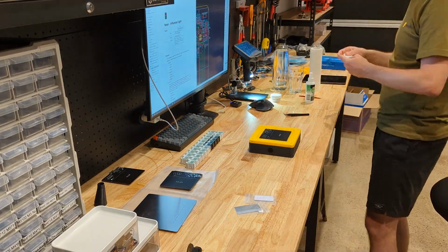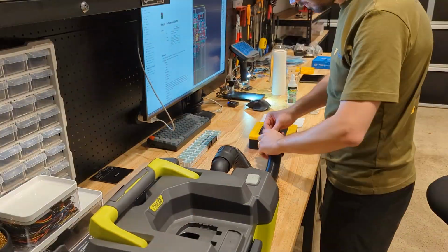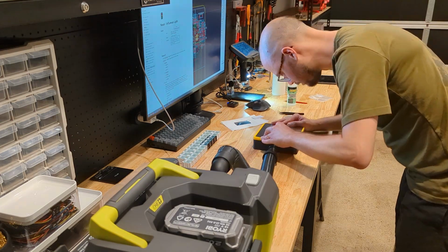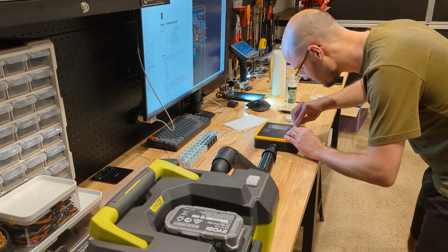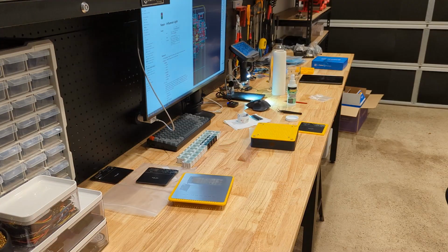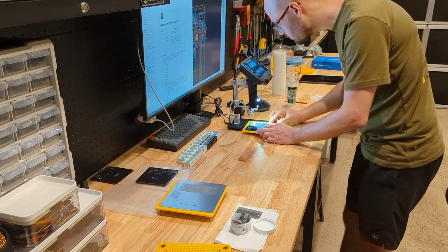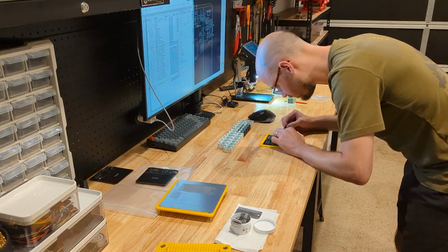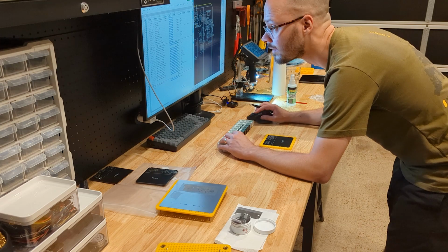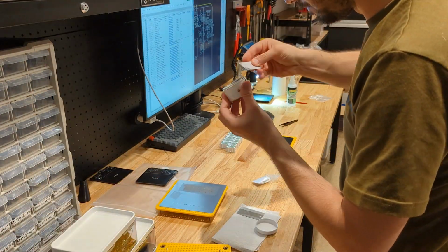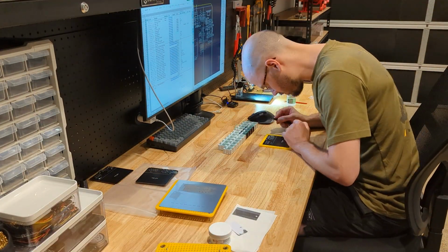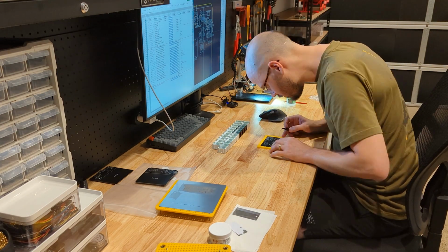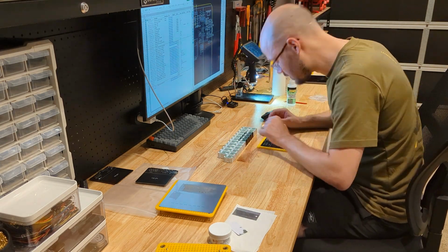Next up is assembling the PCB, and I'm using the stencil fix that I created in the previous video, and I'm really happy how that is working. It's so much simpler to apply the solder paste, and the result is really good. All that's left is now to place the components on the PCB. It takes quite some focus to not place the components on the wrong pad, so I have to double check a lot with the schematic and the layout to ensure that I'm placing the right components.